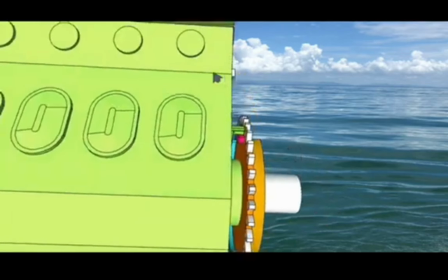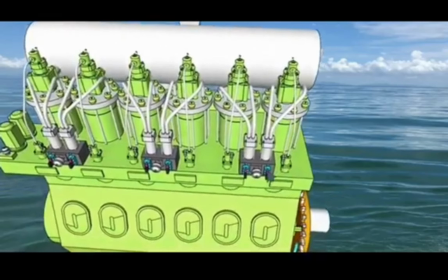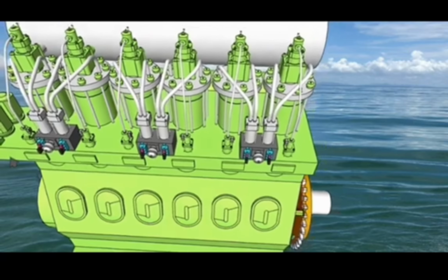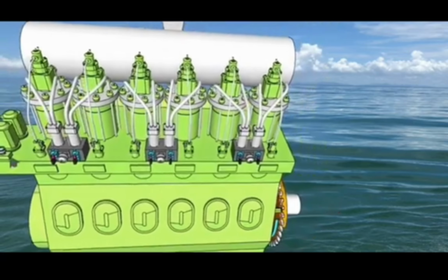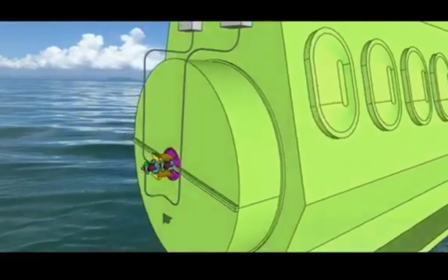The next setup is the hydraulic control unit. For 2 cylinders, there is 1 hydraulic control unit, which will accommodate 2 fuel pumps, the electronic fuel injection valves, plus cylinder lubrication. These are the high pressure pumps, and all the high pressure pipes will be fitted inside the crankcase for safety reasons, so no high pressure pipe will be outside. That is very important. And this is the accumulator for giving a stable hydraulic supply.